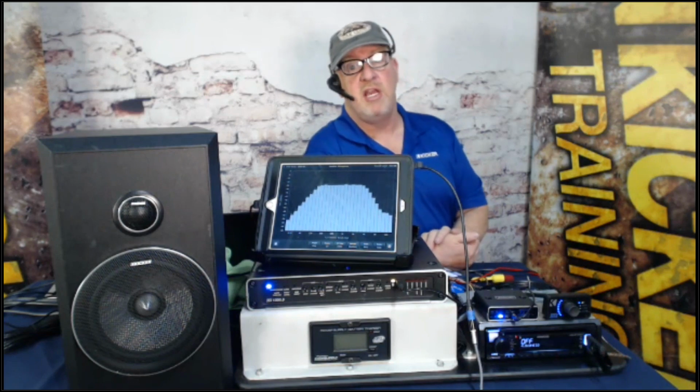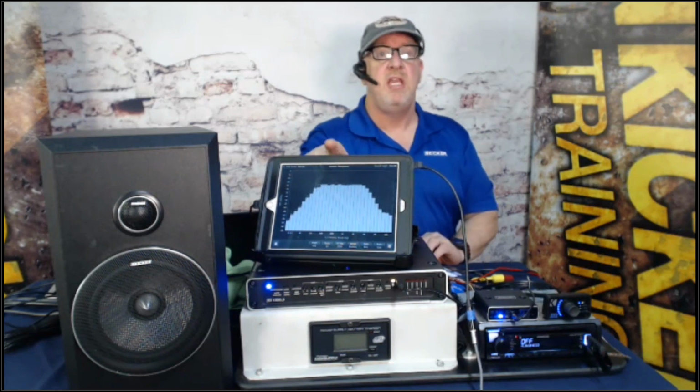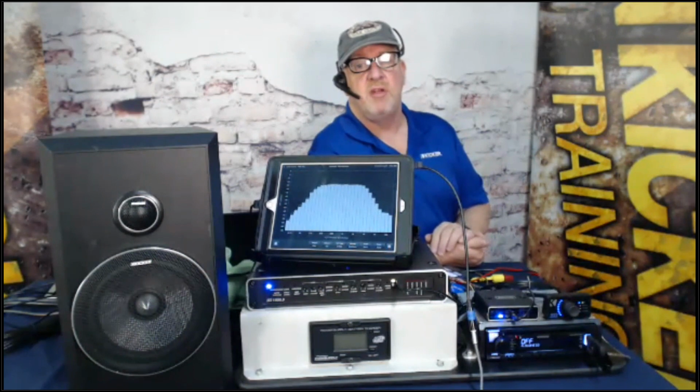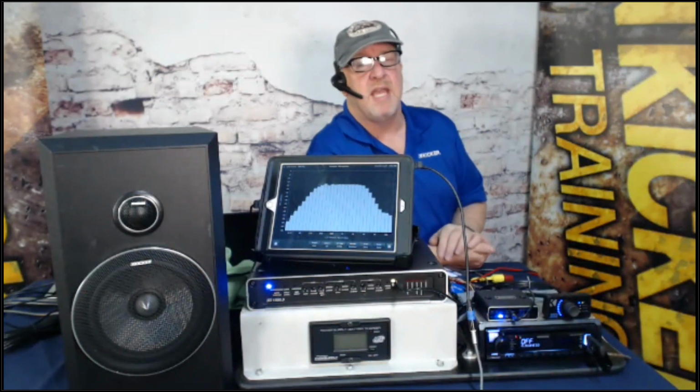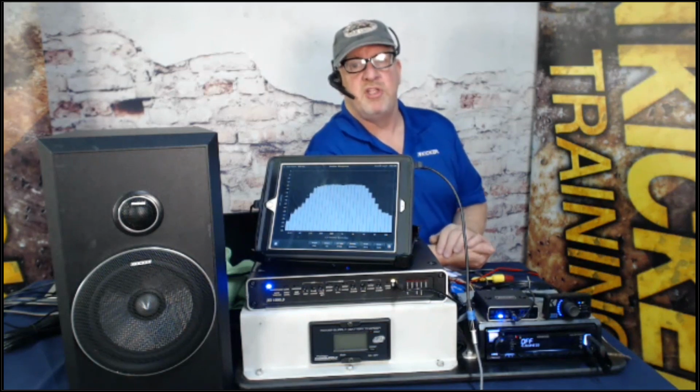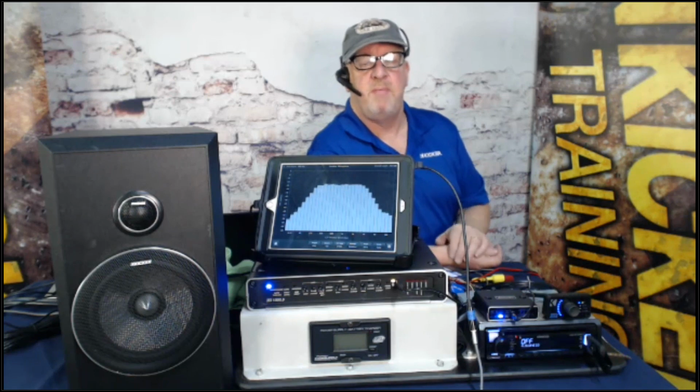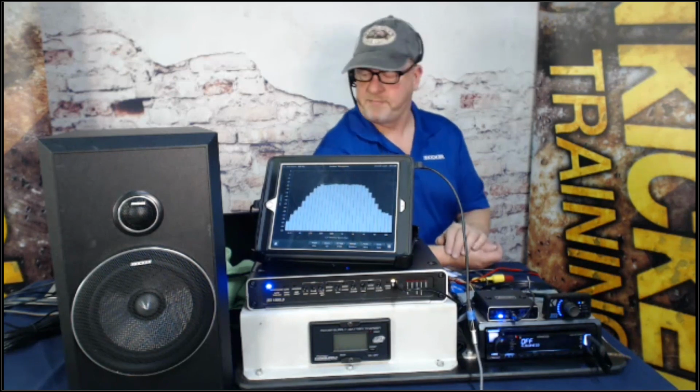tools besides your screw gun you're going to have in a shop. You need to use that RTA. You need to measure the outputs, because it might sound like it's got a lot of bass coming from a door, but if that signal rolls off, you will not get that proper subwoofer output that you're looking for. The system is not going to be playing to its full potential.